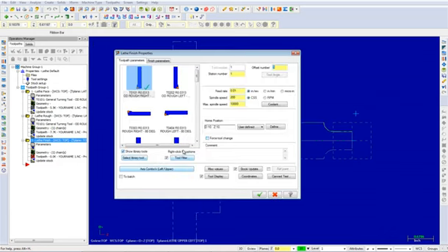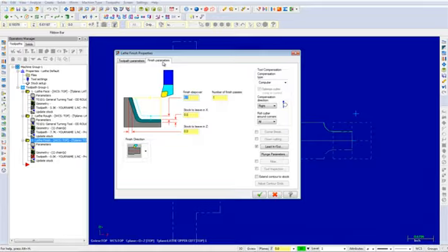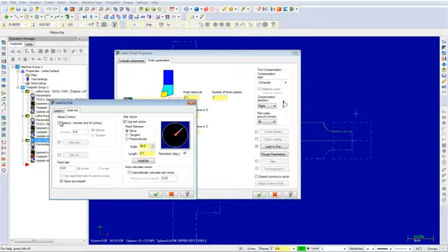From the tool list, select the OD 55 degree right tool and input the comment Finish the OD. Now select the Finish Parameters tab and make all the necessary changes as shown. Click on the Lead In Lead Out button, choose the Lead Out tab and extend the contour by an amount of 0.125. Select the OK button twice to generate the toolpath.